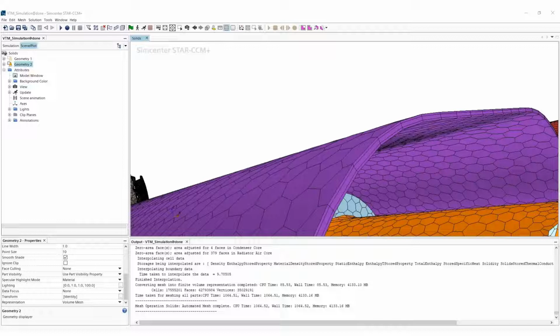The next step would be to run the simulation with the updated heat shield. The solution need not be erased from the base file. We can continue solving the existing results with the updated heat shield, and the results will converge a lot quicker to take into consideration the new heat shield in the model.